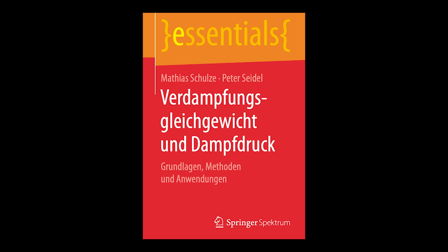The column forces repeated vaporization and condensation cycles. It acts as a cascade of tiny individual Raoult's law separators. Engineers call the effective separation unit a theoretical plate. And at each theoretical plate, a new liquid-vapor equilibrium is established. Which means at each stage, the vapor becomes progressively richer in the lower boiling component, moving upward, while the liquid becomes richer in the higher boiling component, moving downward. By creating dozens of these plates, the column can achieve extraordinary purity.